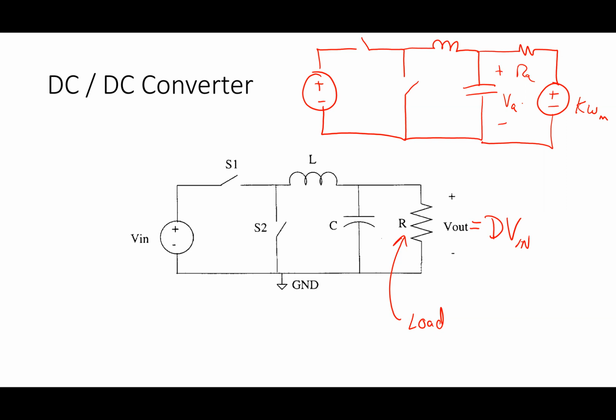Why not? Well, it turns out the motor has its own low pass dynamics, so that if I give it a really high voltage or a really high frequency voltage, the motor only really responds to the average. It doesn't respond to the ups and the downs in the voltage that I apply. But I don't want to get into all the details on that. That's a little bit more detail than we need. Bottom line is this is how I create a variable power supply. And so power electronics are basically in everything at this point.